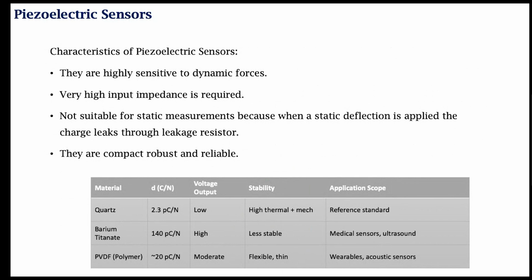This is why piezoelectric sensors are extremely reliable for dynamic measurements, but are quite unreliable for slow varying or constant or static measurements. They're usually really small, compact, and they're very reliable and robust.